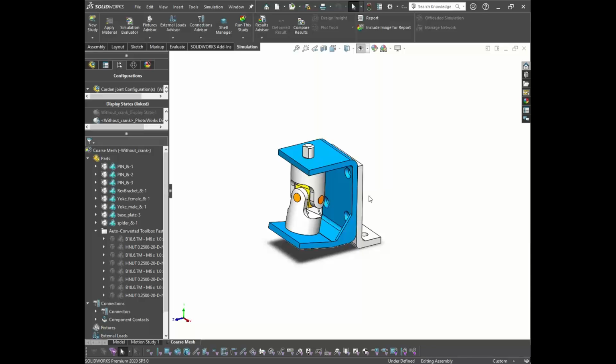But when I define the local no penetration contact to the smaller block, it allowed it to move slightly, but we have not defined any contact to the bigger block. That is why it has considered the global contact that was predefined and glued it to the bottom plate. Okay. Understood, or shall I move to that problem again?